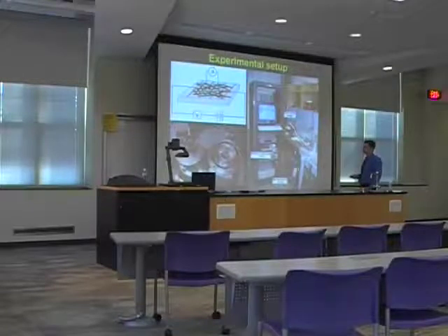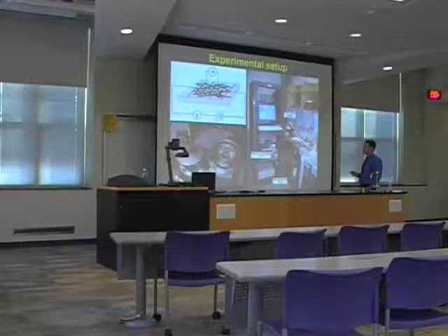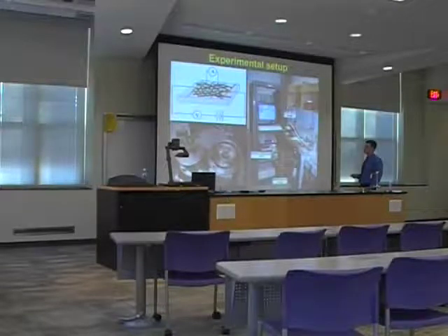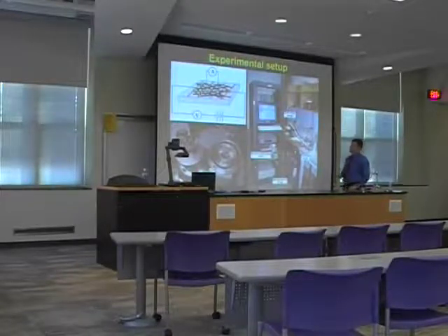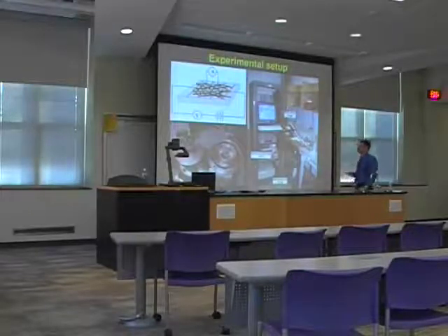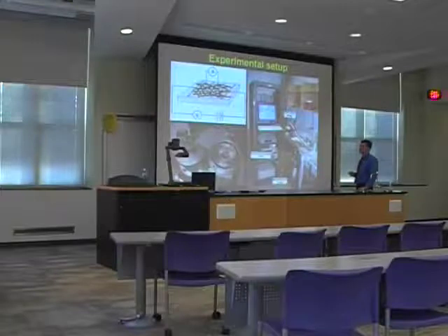It involves a system of vacuum pumps, a small vacuum chamber, some source measure units, lock-in amplifier, multimeter, and a computer basically, with some software like LabVIEW or TestPoint. And this is how the device looks like. So this is a mat of nanowires with gold leads on the top.